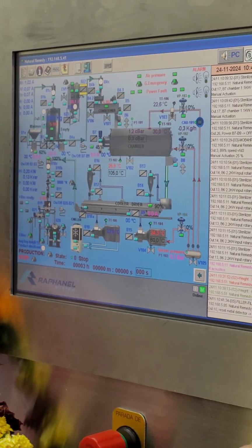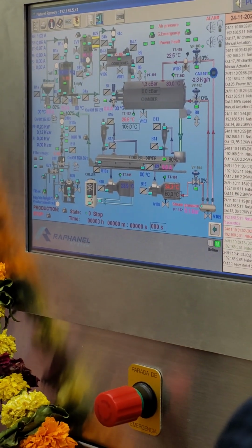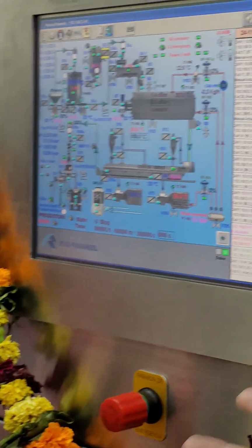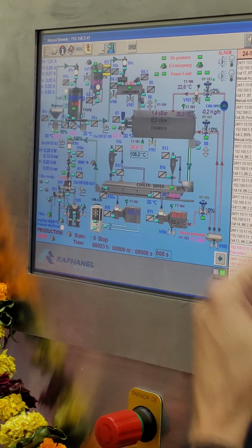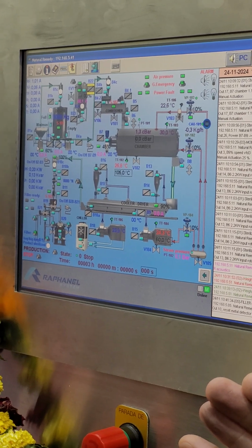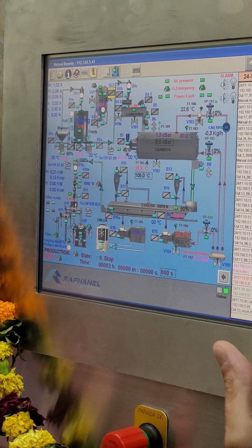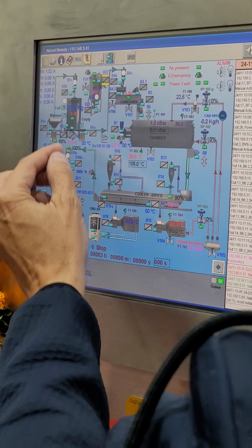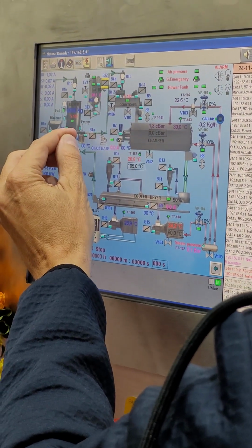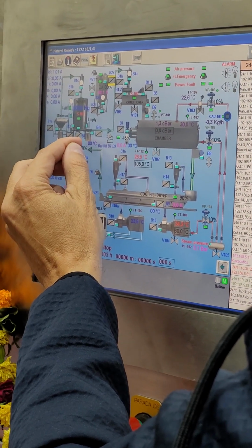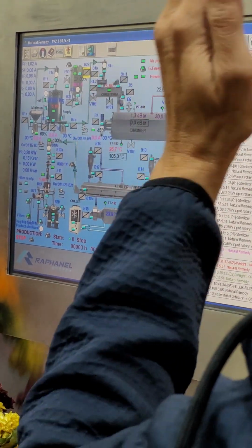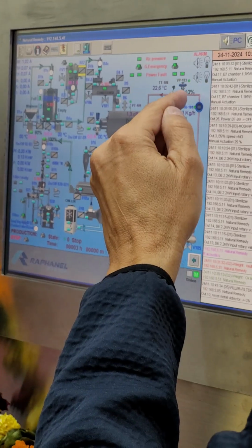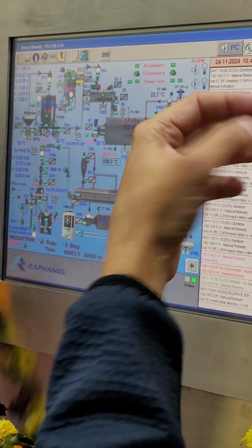Another example. The doser has load cells. Why are the load cells important? It's important because we need to know when to cut the steam. We have to cut the steam when the doser is at 0 kg, no material, and a few seconds later, 1 minute later, and then cut the steam. If you continue injecting with no material, you have the same problem.